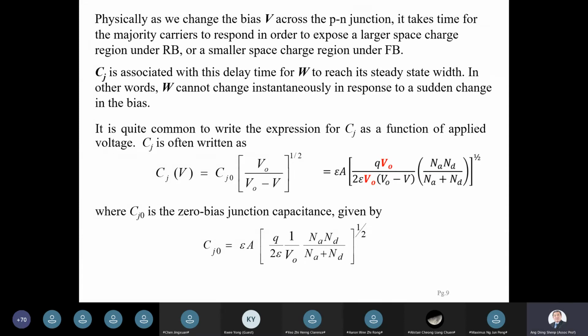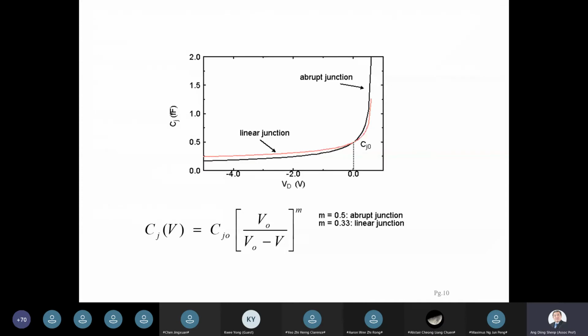In other words, the doping concentration changes linearly from one region to another. What this slide is trying to compare is the result we obtain for an abrupt junction, which doesn't really exist in practice, to the linear junction or linearly graded junction, which is more indicative of a real p-n junction.